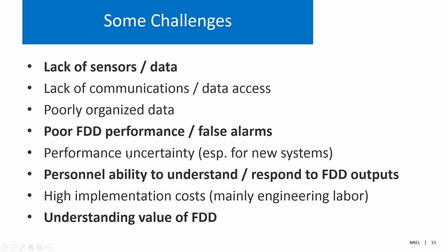One that I've already talked about is this lack of sensors or data. There are lots of cases where it's difficult to get access to the data that you need to really perform adequate fault detection and diagnosis. Either the communications isn't available, or the company doesn't want you to access that data, or the sensors just don't exist.